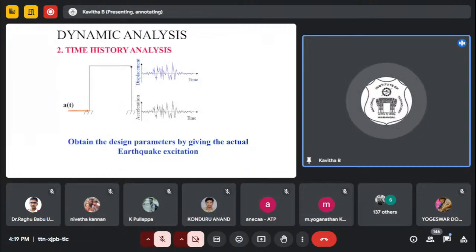Here the time history method is another option. Time history takes the earthquake data which are getting recorded. Already we have seen the need for recording and how people are recording these days. Those recordings will be given as an input to this building and we will study its response. For example, if that building is going to survive that particular event, in terms of the acceleration profile, then we can say that in the future also it can survive this kind of waves.